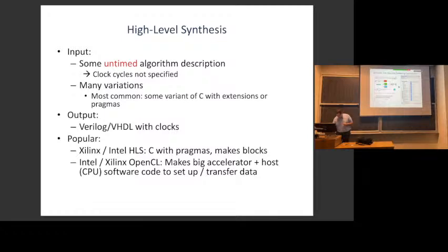Okay, so from a block diagram like this, the input to the high-level synthesis is not C with a bunch of extra pragmas or OpenCL constructs. It's actually a block diagram. But for every one of the important blocks in Simulink for signal processing, Intel, for example, has gone off and written an IP core. IP core means intellectual property core. It just means a block of parameterized hardware. Behind the scenes, it's a bunch of HDL, but you didn't write the HDL, you just asked for it. So it's like a library call, but for hardware.